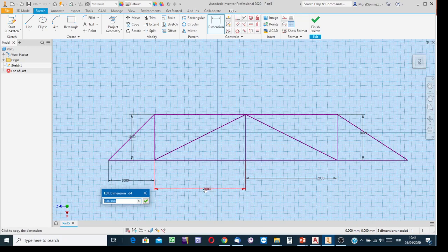If the width of the cell, for instance, were greater than 2000, then under the action of gravity force, the deflection of this member will be a little bit more. I don't want to have such a deflection order. So select the length of the member in this order.